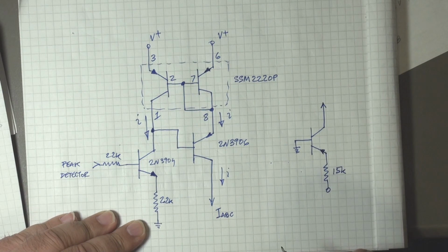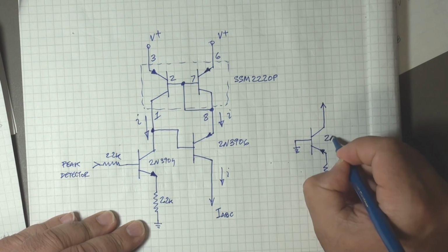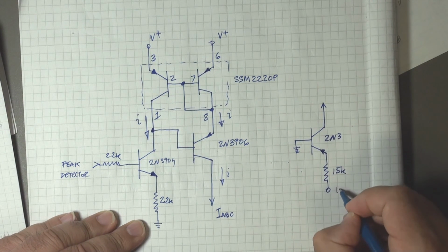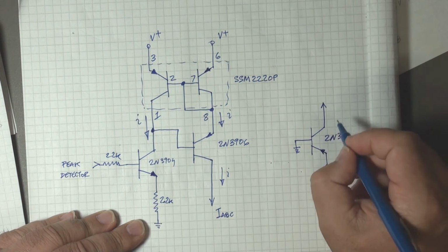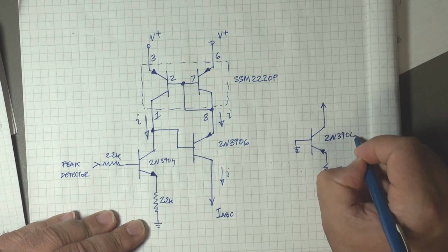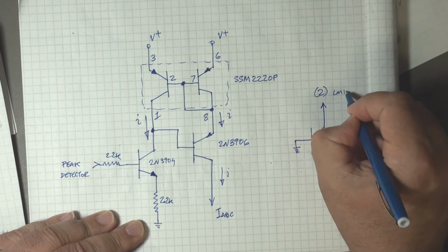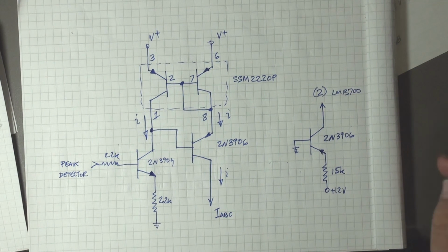So this is not a part of the signal processing, but a 1 milliamp bias current, thereabouts, flowing into pin 2 of the LM13700 linearizes the output, it reduces distortion, basically.